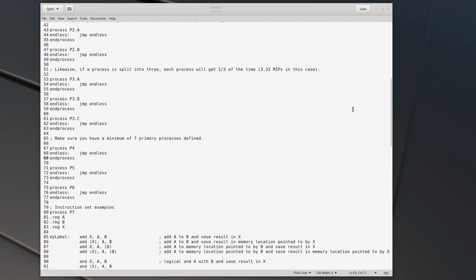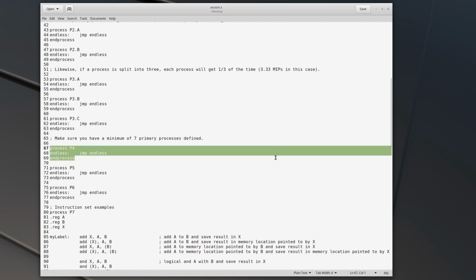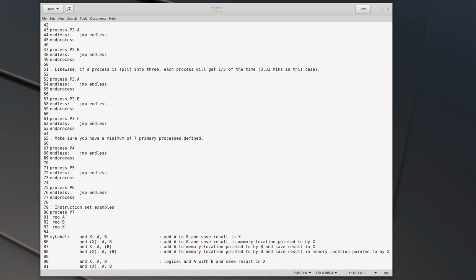One example where you're going to need plenty of processing power of a primary process would be, for example, scanning an array of WS2813 pixel LEDs. These will take 10 MIPS of processing power to do that. However, for something like a 9600 baud UART, you'll find that 1 or 2 MIPS of processing power is all that you need. In this case, a 10 MIPS primary process could easily be split into 10 sub-processors, and you could have 10 UARTs running at 9600 baud with no problem.